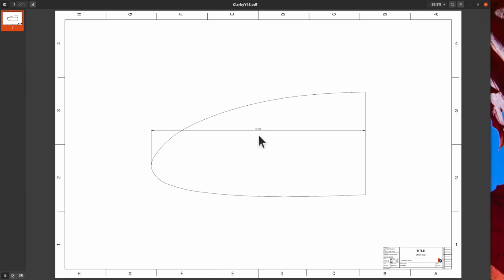Do I have 18.968 inches? Sometimes you won't. So if that's the case, then what you're going to have to do is figure out a scaling change on the printing device itself. So let's say you figured out that it's measuring it just a little bit small. You do the percentage calculation, so whatever your measurement was, divide it by what it should be. That's going to give you a percentage. Let's say it was 99% of what we really wanted, so it's 1% too small.